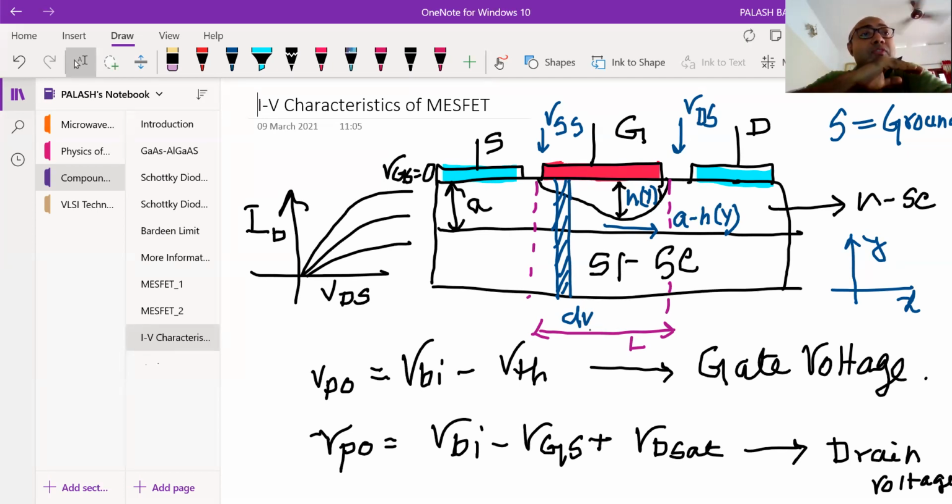So it is very prone, and the electron mobility across any surface is reduced. Why? Because at the silicon dioxide interface, or silicon or any other gate oxide interface, a lot of defects are there, a lot of capture zones are there. So they are going to capture and disturb the flow of the electron, and that is why the mobility will decrease, right? These things will happen if you have a surface device where electrons flow across the interface.